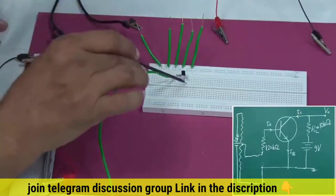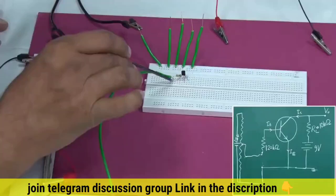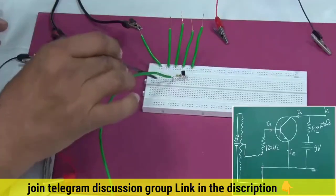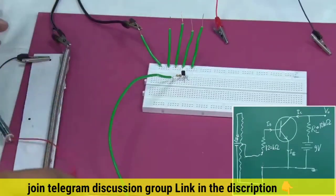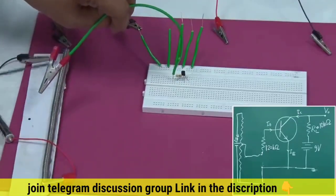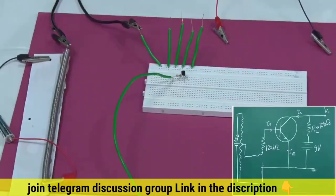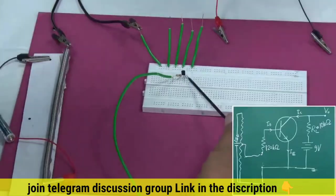I have the base. From the base, I have added 120 kilo ohm of resistance. From there, I have added this variable point, which I will be connecting somewhere, and then this will be our input voltage. Now, the emitter has to be connected to the ground. Where is the emitter? This one is the emitter.